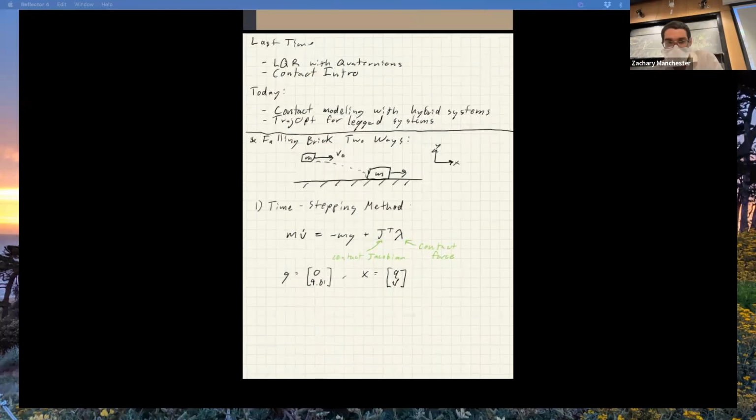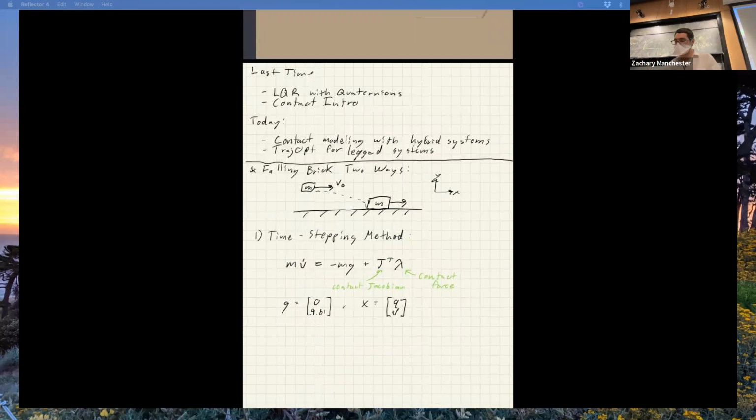And then we've got, so this is the dynamics. Then we've got this other thing that's going to go along with this. It's a constraint that we're going to write down in terms of this function. The standard notation here is phi for this thing called the signed distance function. And I'll just write it down real quick for this problem. We can talk about it. So if I have q, which has the x and y components, this thing's actually our Jacobian J.